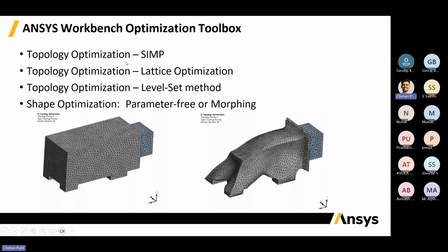But the SIMP optimization is totally different because it is a density based optimization. So your body's density will be calculated and then those materials or elements will be removed from the geometry which have a low density, or which are not capable of performing the conditions for whatever application we are using the model for, if those elements are of no use for that kind of work we are trying to do.